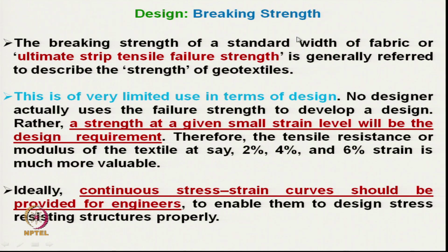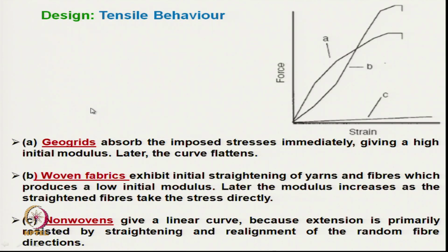Ideally, along with the breaking strength value, continuous stress strain curves are required for the engineers to design the structure. So, we must provide the continuous stress strain curve for the geotextile. Here we can see the tensile behavior of geogrid A, woven fabric B and non-woven fabric.